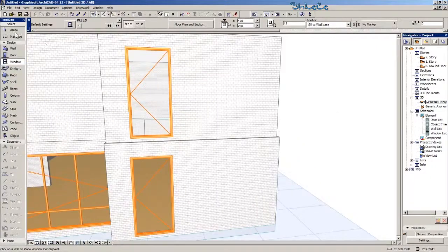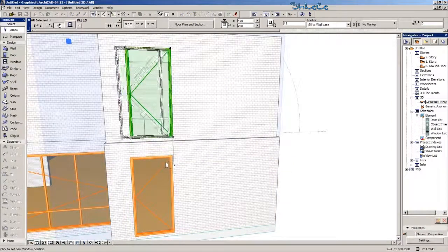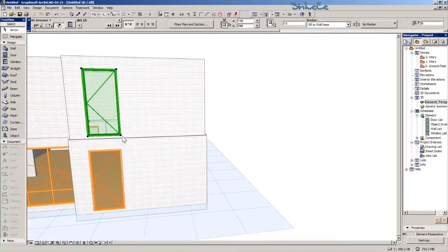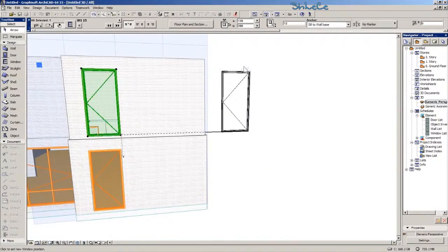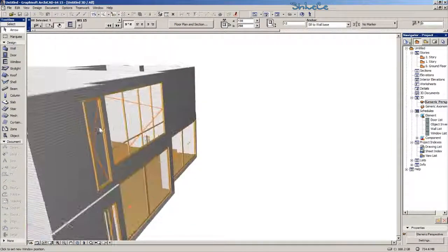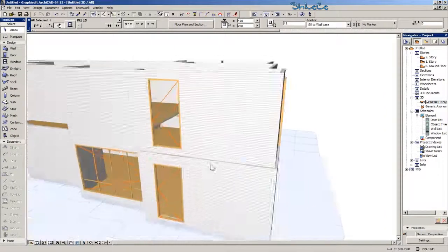Now let's select it, select this point. Then I'm gonna select this one, that is drag, and press and hold down shift and match it to this one. Now I'm gonna select this one again, this time select the elevate and make sure that its starting point is the same as other windows. So now this is fine.